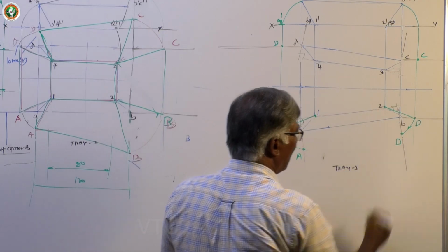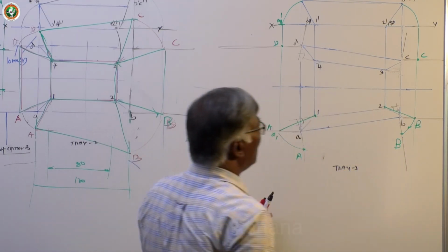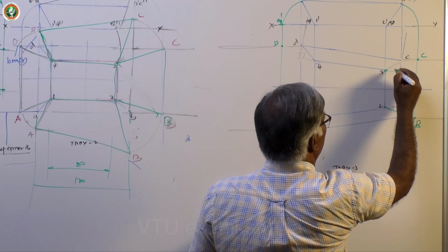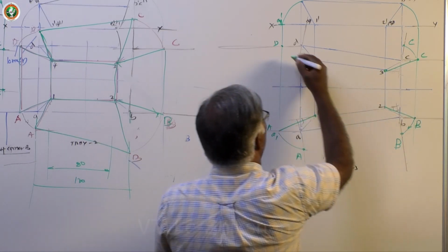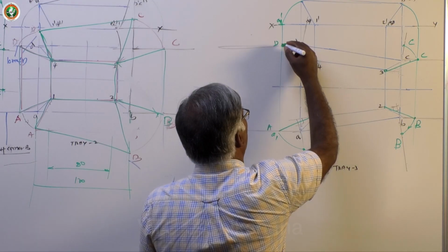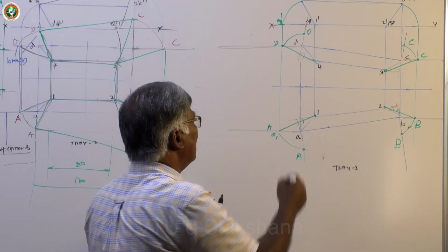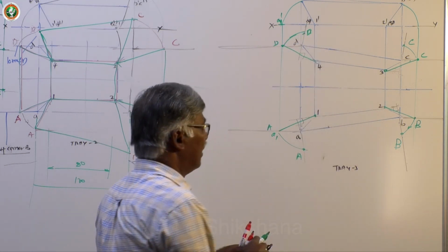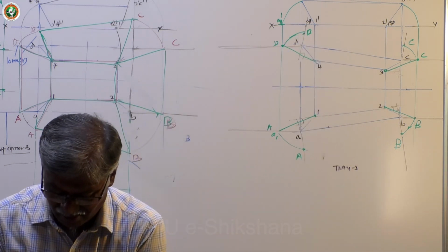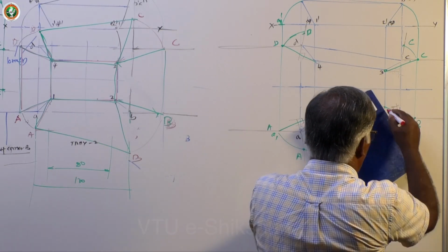This is capital B. Next, C. Again, see how to do it. Again, 3A as center, this is the length. Draw an arc. This is C. Similarly, this is the actual length. Then transfer this to here, or draw an arc, and get D. Now all the points we got on the respective loci, join them. That's all. So we got the actual development.